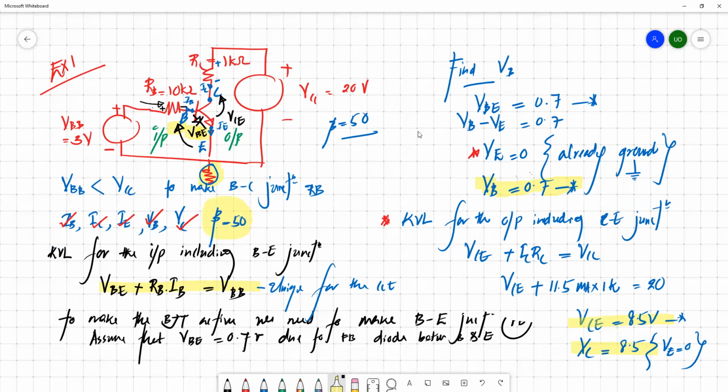For example, let's think that the transistor data sheet gives VCE max equals 25 volt. Just think, in the transistor data sheet it's given that VCE max equals 25 volt. What's this VCE? This is your VCE. So for this particular circuit, now you have an idea about what kind of circuit you are implementing. You are planning to include a collector resistor. So what would be the value of VCC?